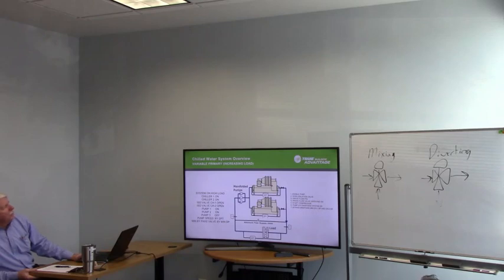When we want to bring the second chiller on, we always turn on another pump first. Okay? Always err on too much flow rather than not enough flow. So we open the isolation valve, we prove flow, approve the end switch, start the compressor, and the bypass will maintain the minimum flow.